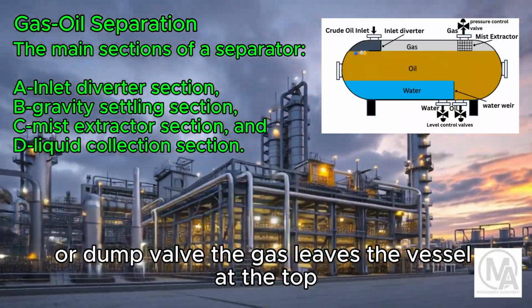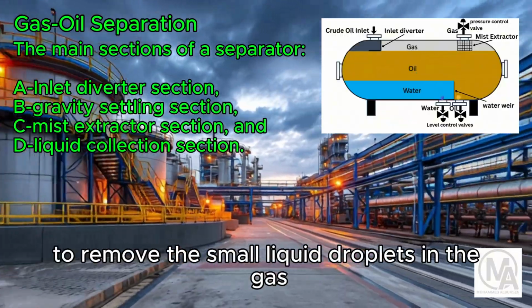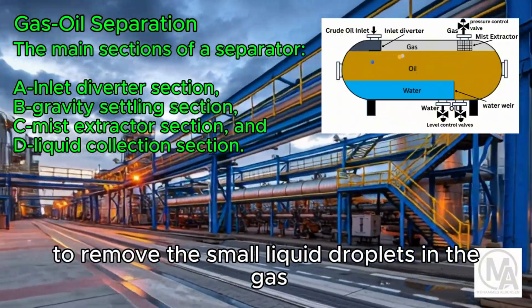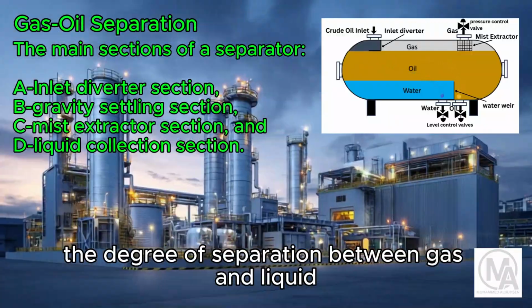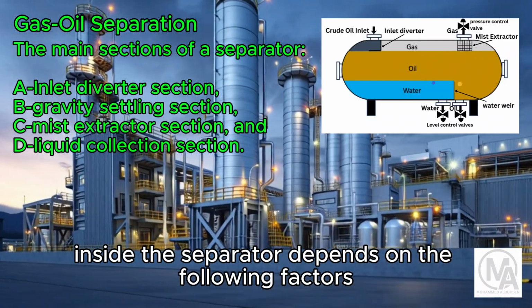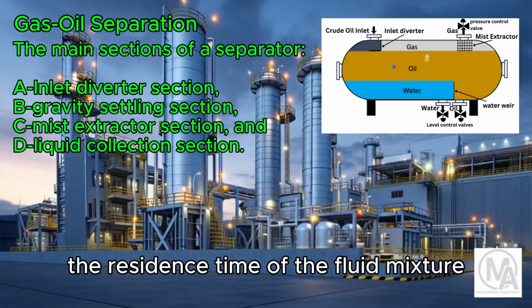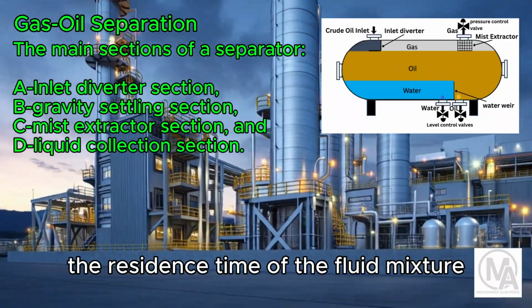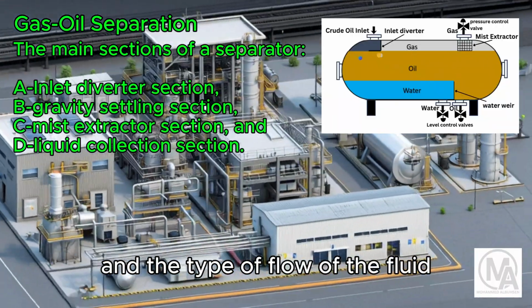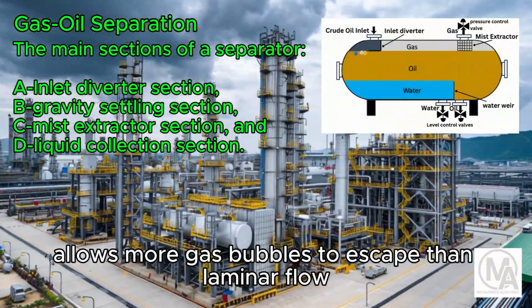The gas leaves the vessel at the top, passing through a mist extractor to remove the small liquid droplets in the gas. The degree of separation between gas and liquid inside the separator depends on the following factors: separator operating pressure, the residence time of the fluid mixture, and the type of flow of the fluid. Turbulent flow allows more gas bubbles to escape than laminar flow.